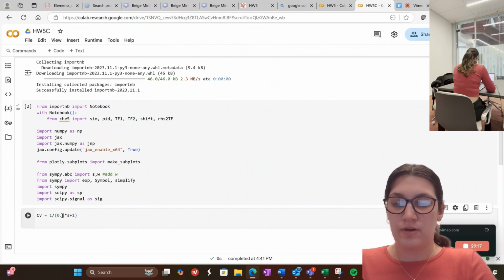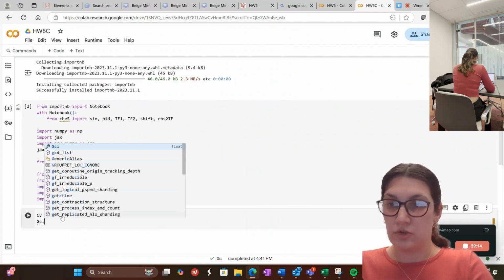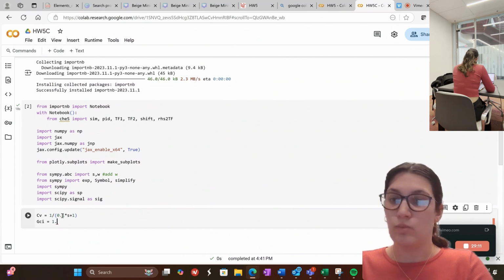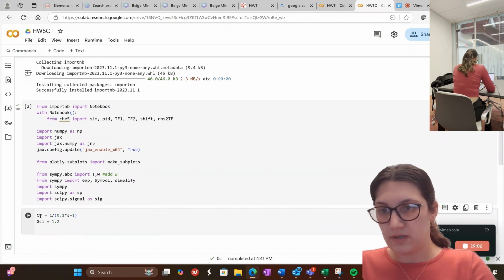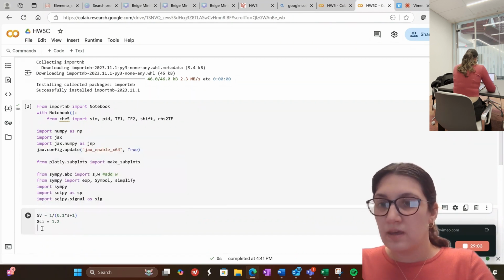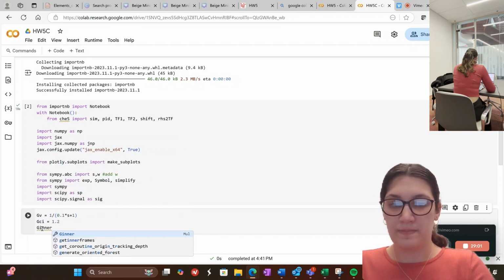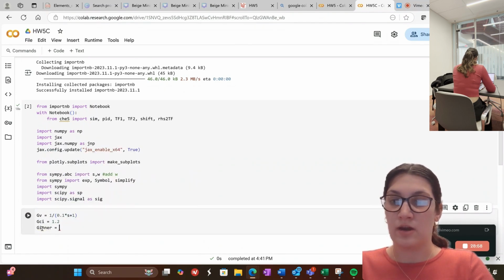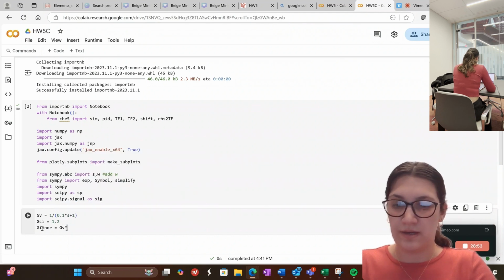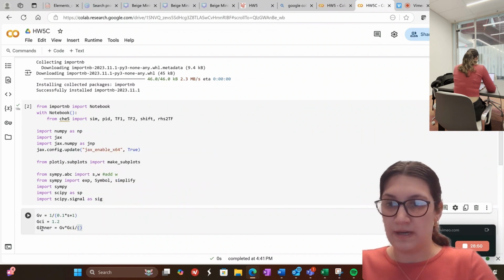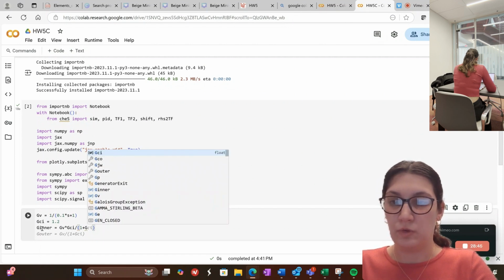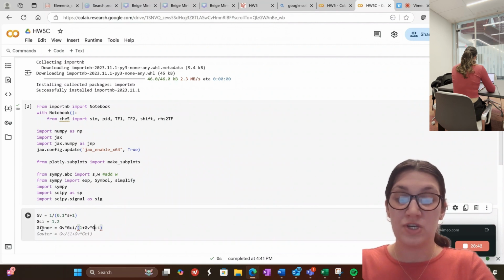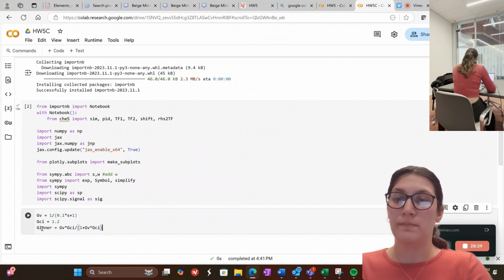And then our inner controller gain is 1.2, which was given to us. Our G inner is everything across the front multiplied together, so GV times GCI divided by 1 plus everything in the entire loop, so GV times GCI, since our measurement we are assuming is 1.